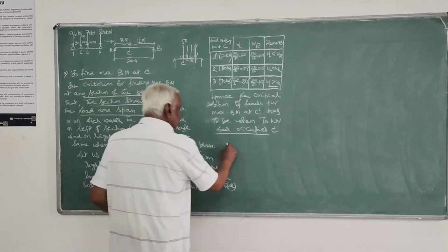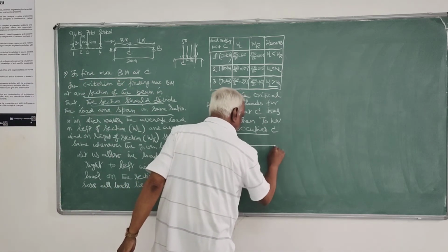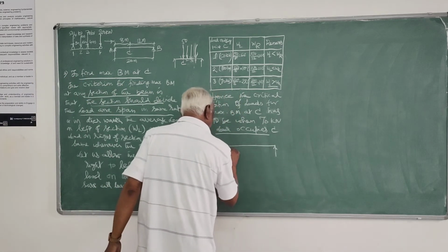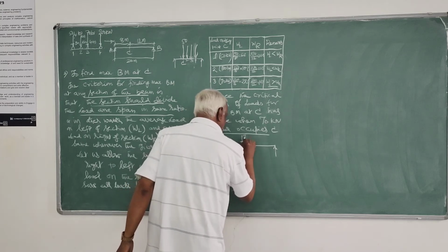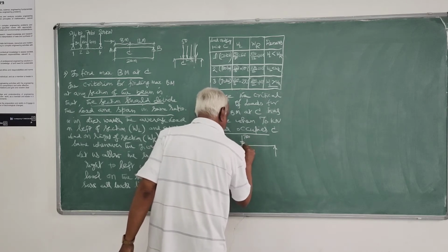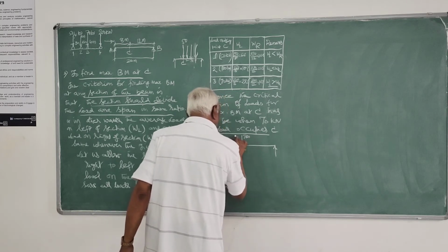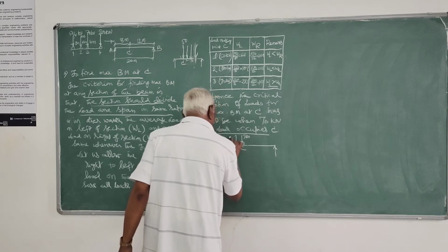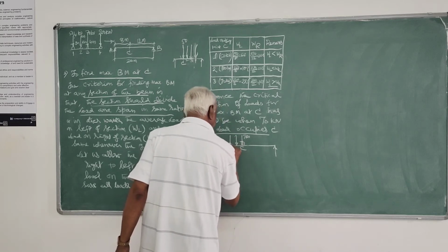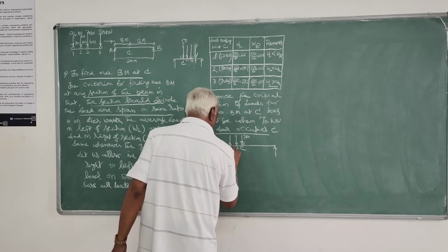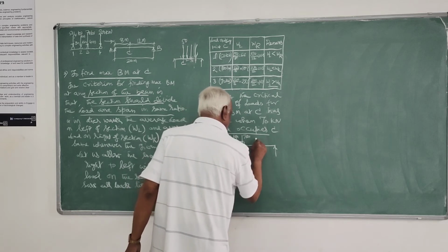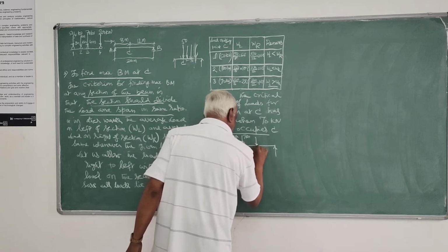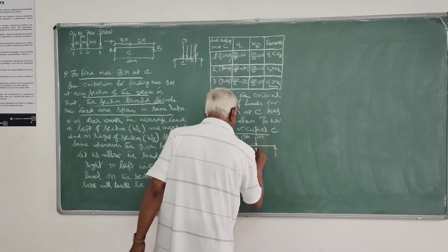So that means the position of the load to get maximum bending moment at section C has to be that load 3 is at this point, and the other two loads would have crossed the span, and 50, 100, and 200 will still be on the right side.